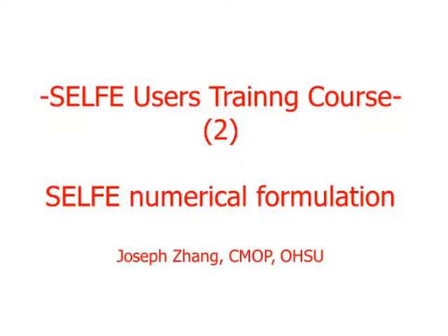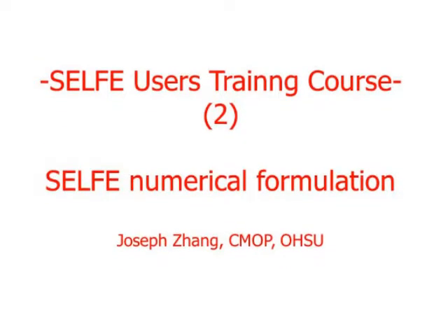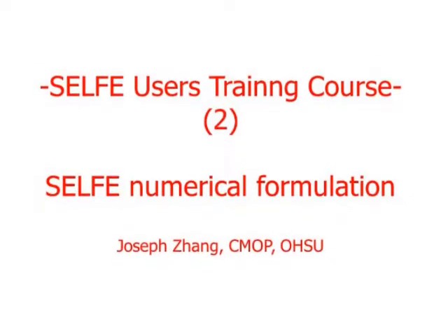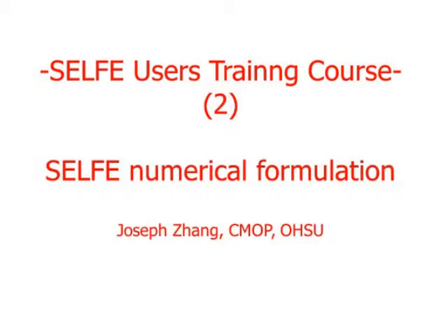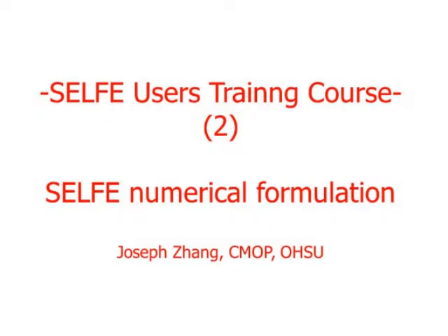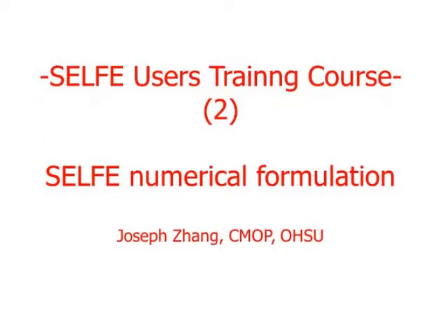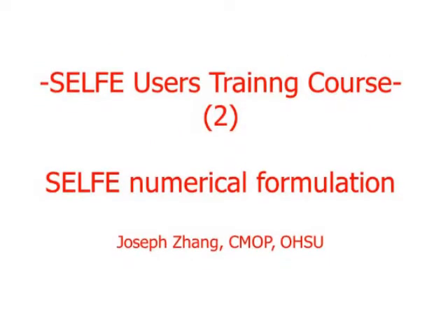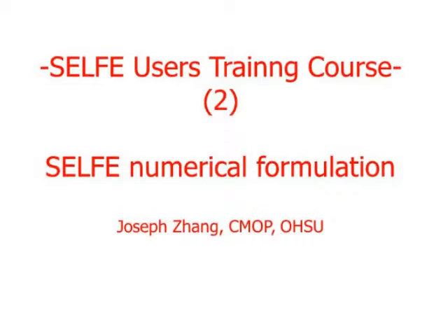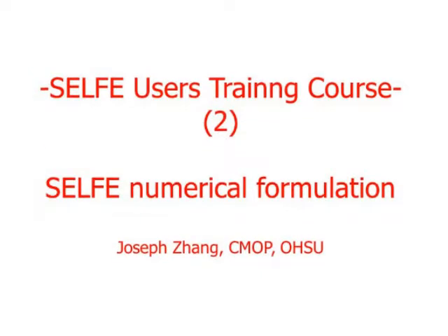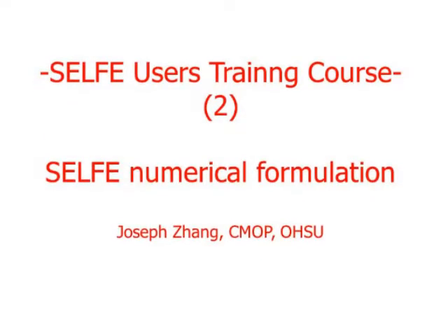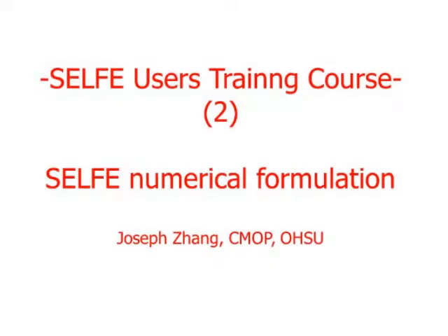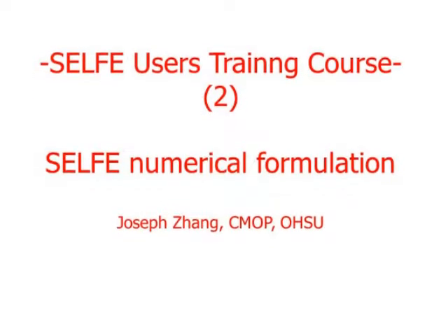On the bottom, you can see the one-dimensional case, the linear hat function and quadratic functions. And in 2D, you have the traditional linear hat function in the conformal sense. The second picture shows a little bit non-conventional, non-conformal hat function, which is discontinuous at each node and continuous at side centers.